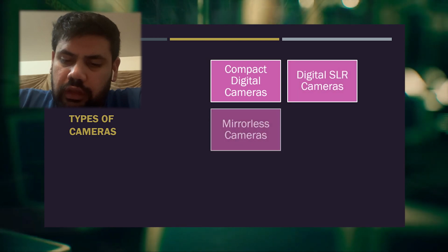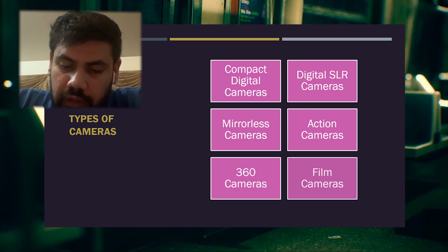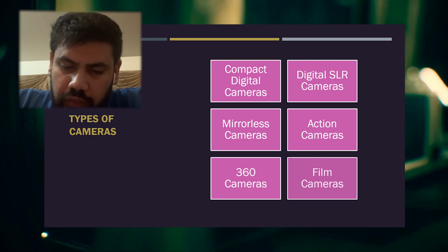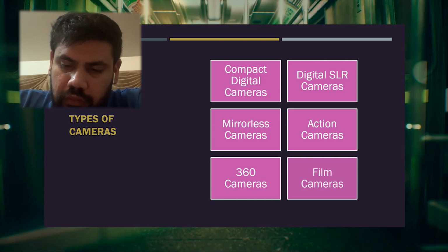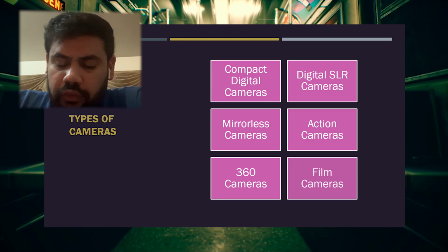Types of sensors. The most common types of sensors are CCD, charge coupled device, and CMOS, complementary metal oxide semiconductor. CCD is one of the oldest image capture technologies for digital cameras and has long offered superior image quality compared to CMOS sensors, with better dynamic range and noise control. CMOS, on the other hand, has been considered an inferior competitor to CCD, but today's CMOS sensors have been upgraded to match and even transcend the CCD standard with more built-in functionality than CCDs. CMOS sensors work more efficiently.